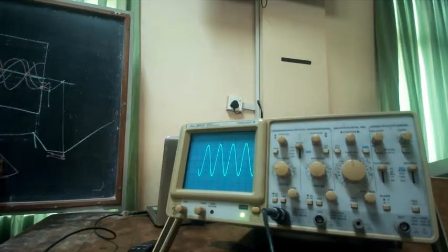The signal comes here, and the output controls the sweep signal. It switches on and off based on that. It sends a trigger. As soon as you receive this trigger, it produces a sweep and waits until it receives another trigger. And the sweep slope is determined by the time per division setting. Okay? Clear? Everybody clear?